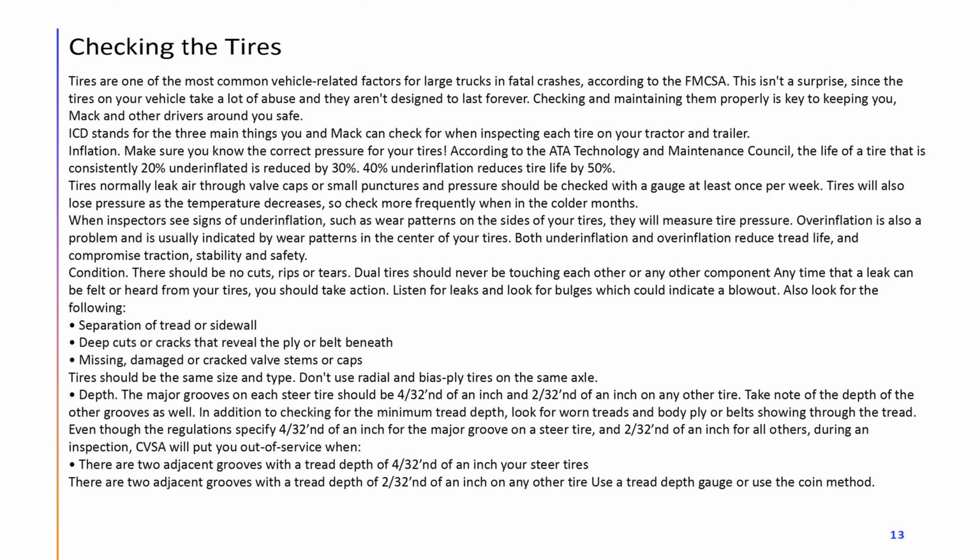When inspectors see signs of underinflation, such as wear patterns on the sides of your tires, they will measure tire pressure. Overinflation is also a problem and is usually indicated by wear patterns in the center of your tires. Both underinflation and overinflation reduce tread life and compromise traction, stability, and safety.